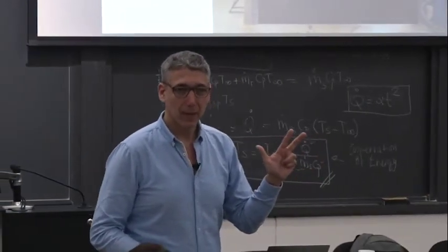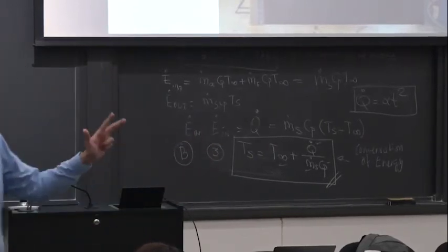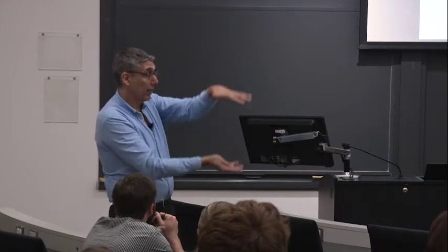Is it the size of the opening? Height. Okay. Height, size of the opening. What are we talking about here? What is the height? What height are you talking about? The height, the free height of the smoke layer, no? Is the area through which the entrainment can happen. Is that okay? The smaller that number is, the smaller your entrainment. The bigger that number is, the bigger your entrainment.